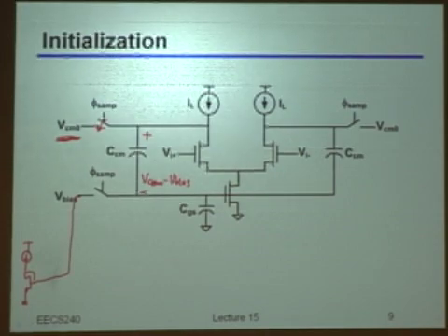So there can be some drift, but from time to time I always enforce the values of the common mode and the charge that I would like that capacitance to have, right? And so basically, since V bias will always stay a V bias, then even when I'm using the amplifier, basically I will have the common mode at VCM0, right? So do you see any potential problem with this, what I've called the brute force approach, right?